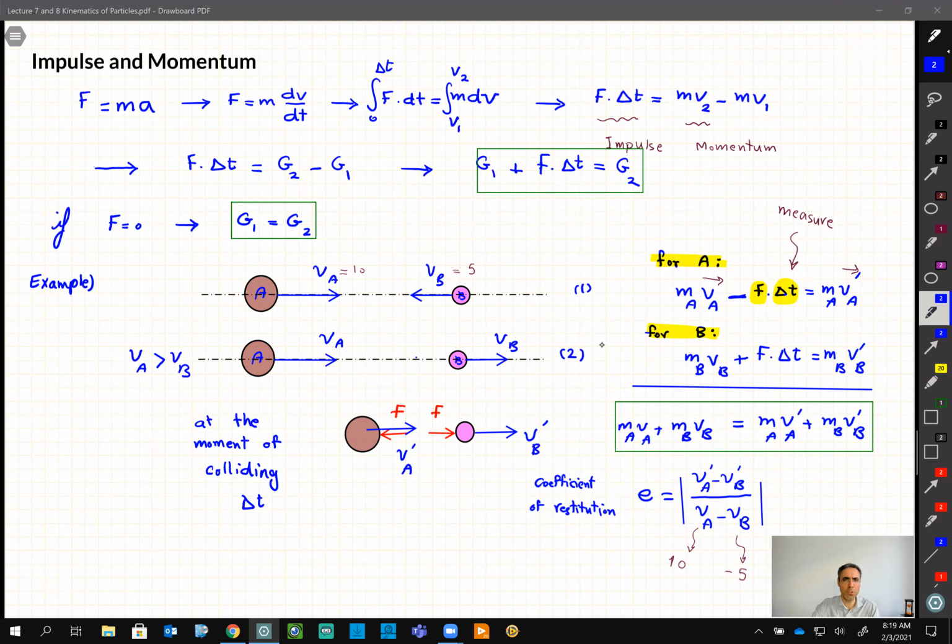So if we have two different materials, and that's in fact a good question. Let's say A and B, two different materials, and also maybe different sizes. Let's say a big ball A and a small ball. There are formulas. If you Google Wikipedia, developed by what they call the Hertz formula, you can put the diameter of these two particles and their material, because for each material we have a value, which I hope by now you guys learned from your MEC 260, we call it modulus of elasticity.